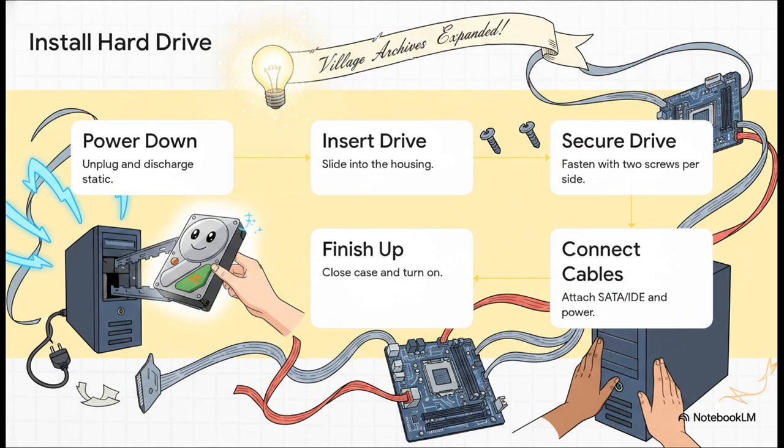Then, connect it to the motherboard using either that thin SATA cable or the wide flat gray IDE cable we talked about. Finally, plug in the power supply connector, close up the case, and turn it on. Just like that, you've successfully expanded the Village archives.